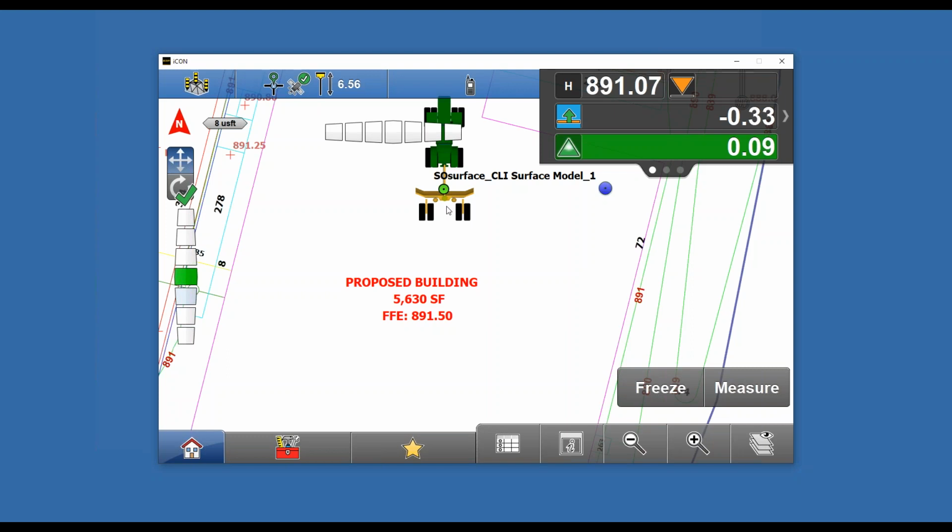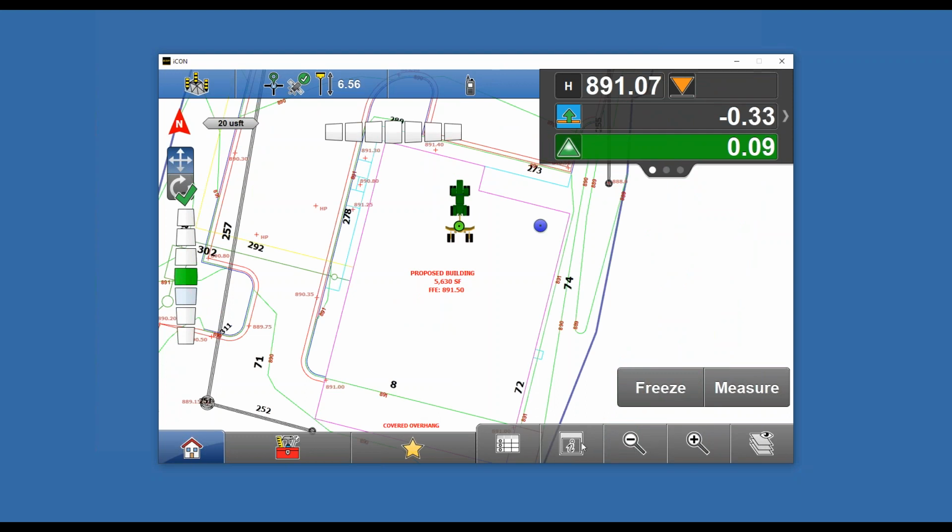It's not like our tilt rover where you can lean it all the way over, but anything you would put a tractor pan on or a D8 or something where you're looking to be within a tenth or two, you're no problem there. You're going to be tighter than that on fairly flat ground anyway. So you do have that option.